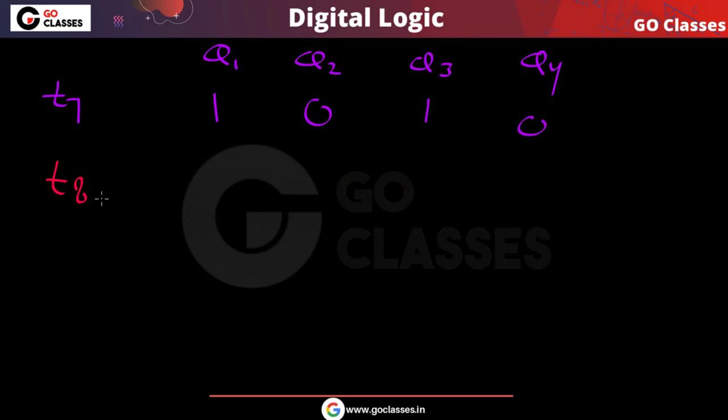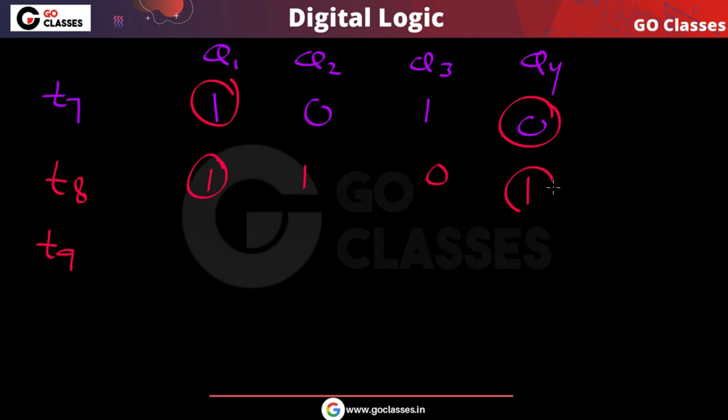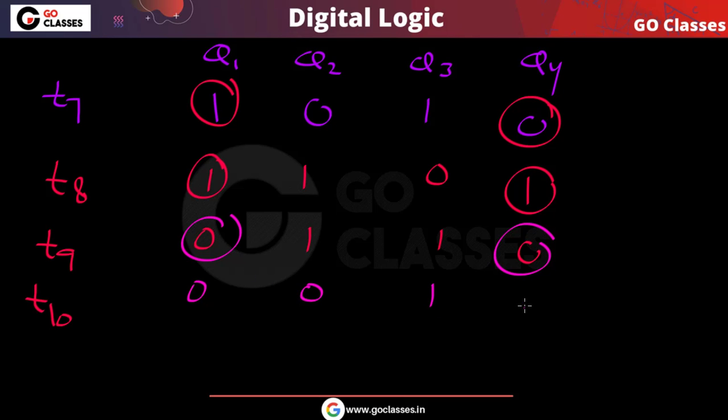Now at time t equal to 8, again this exclusive OR this, so that will become 1, and then this will become 1, this will become 0, and this will become 1. And then at time t equal to 9, this and this exclusive OR, that will become 0, this will become 1, this will become 1, this will become 0. At time t equal to 10, what will happen? This exclusive OR, so this will become 0, this will become 0, this will become 1, and then this will become 1. So at time t equal to 11, what will happen?